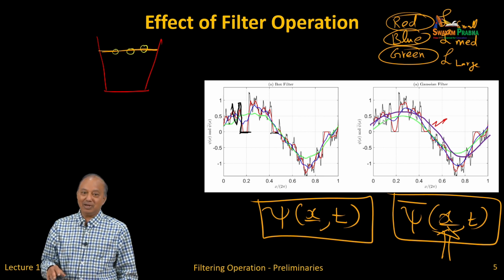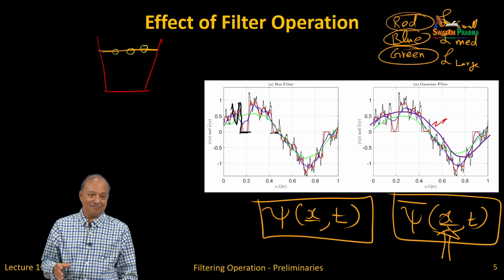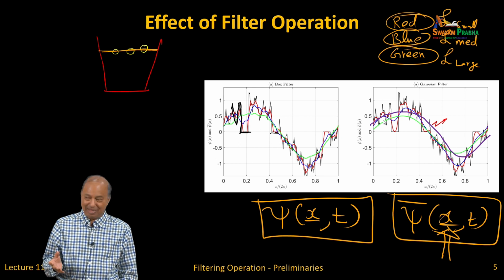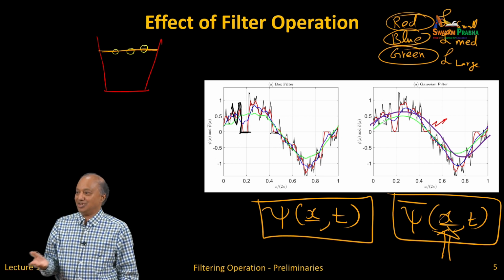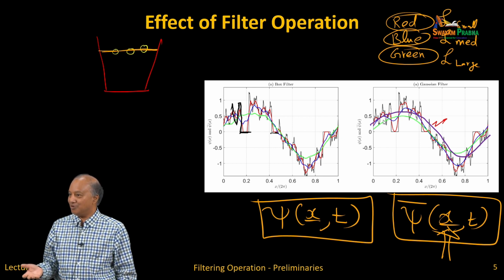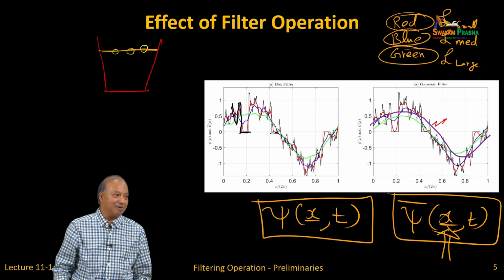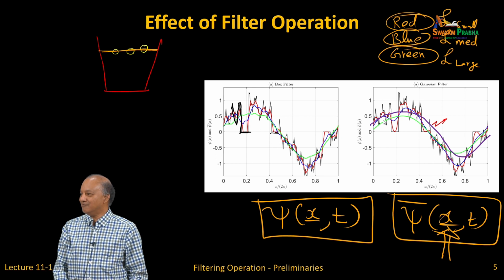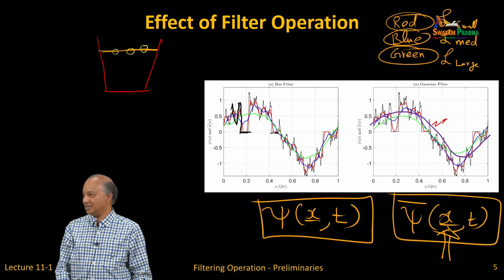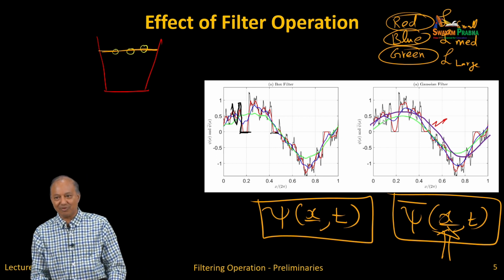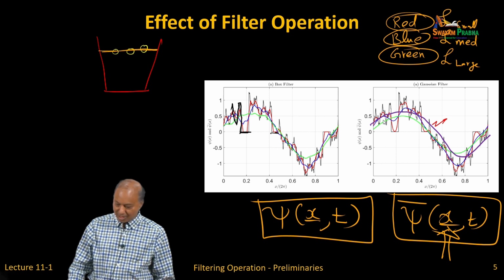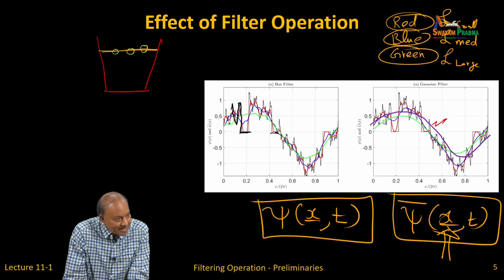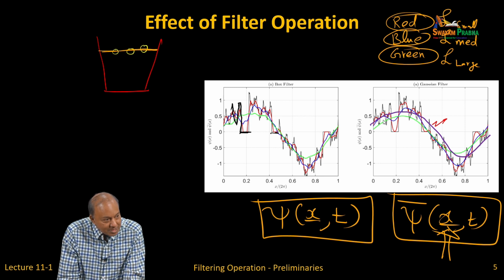So a grid independent study is very hard, in fact impossible with LES, in that the answer changes as you change the grid. So the classical CFD concept of grid independent study is really very difficult. So that is another thing that you might want to think about.